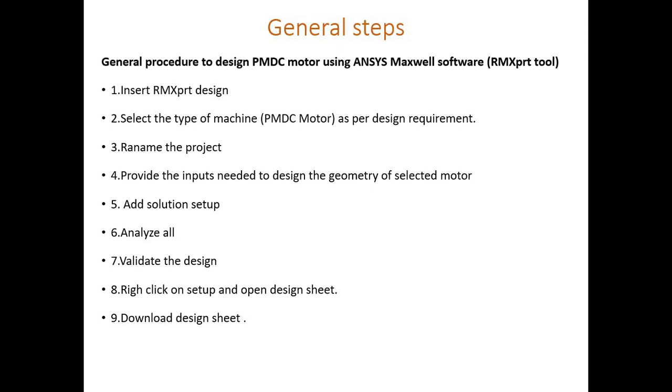While making the design and simulation of PMDC motor, you need to go through a few general steps. First, insert RMXprt design and select the type of machine. Second, select the type of machine, that is PMDC motor, as per the design requirement. Third, rename the project as per your convenience. Fourth, provide the inputs needed to design the geometry of the selected motor, that is PMDC motor in this case.